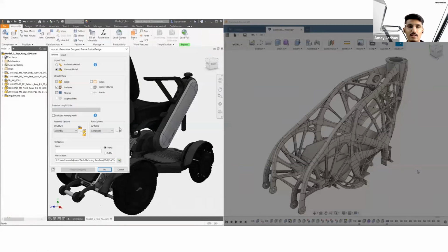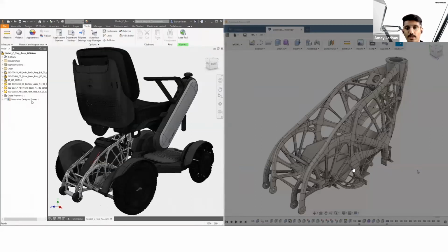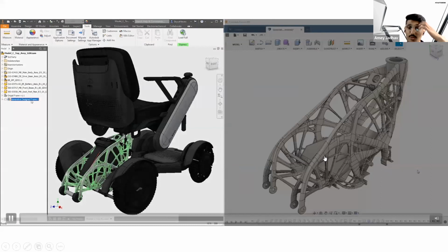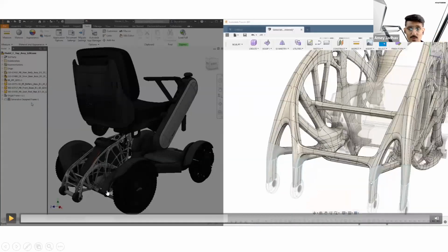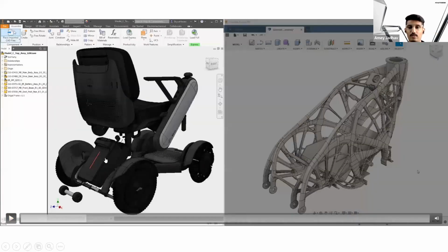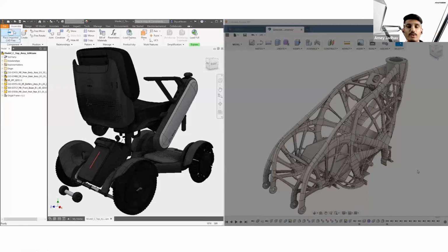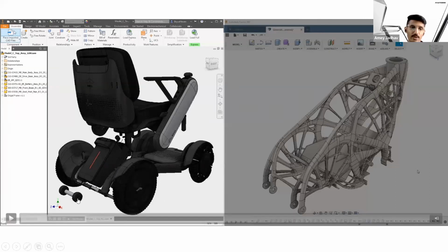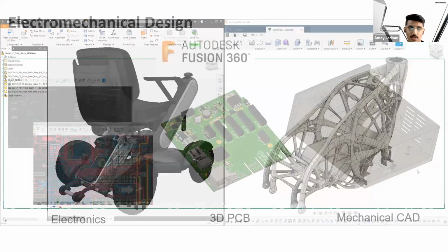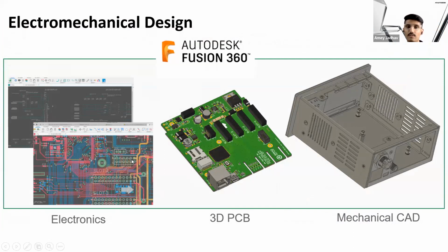The baby cradle back is being replaced with the generative design product. Why do we use that? What's the necessity for using this? As you can see, we have reduced a lot of weight. If it was 5 kgs, we could reduce it to 2.5, so that specific part of the model will be 2.5 kgs after generative design. That means we have reduced 2.5 kgs of weight, which means more efficiency. A person will not be as fatigued if using those things. That's the reason why we use generative design.